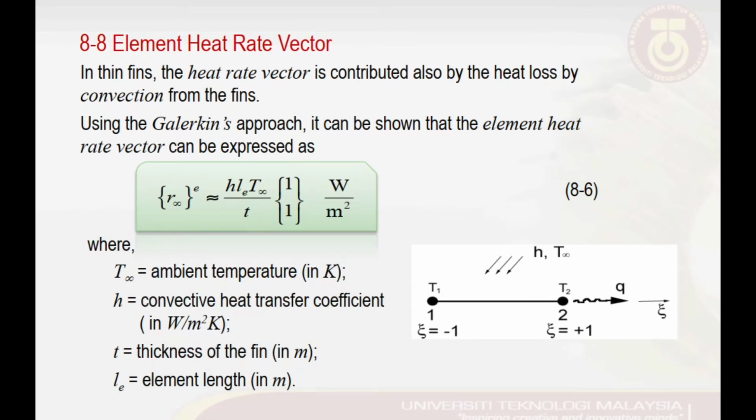In thin fin problems, there are two types of boundary conditions involved. The first one is the known or specified boundary condition, the temperature value at the base of the fins. So considering this is the main body of our system, generating or having high temperature regions.